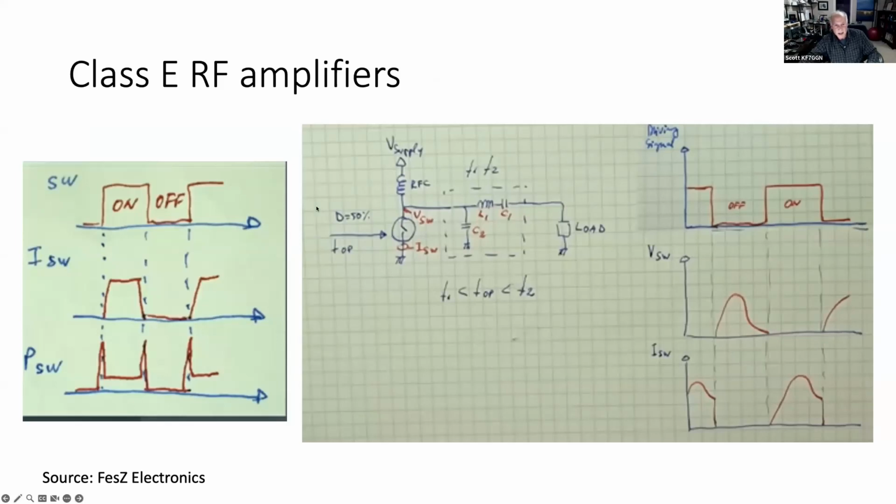Now for Class E, there's a similar type of situation. However, what is done in Class E is instead of 2 transistors switching, you can have a single transistor switching, which already makes it a little bit of a simpler circuit to work with. The main thing here is this LC circuit in the middle. It's supposed to be a filter and also an impedance matching circuit.